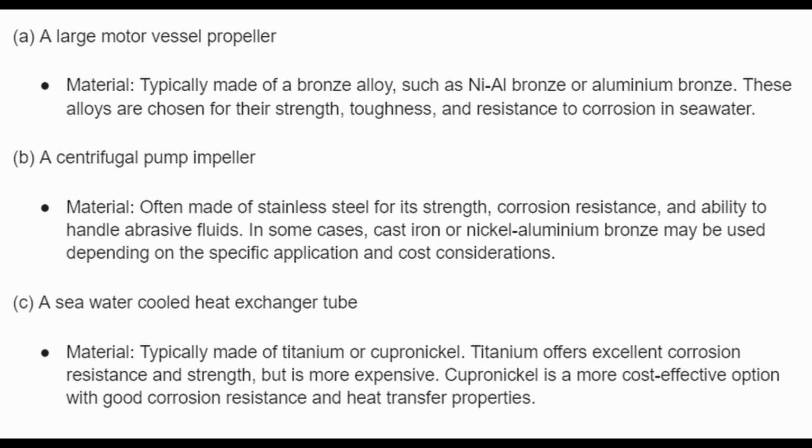B. A centrifugal pump impeller. Material: often made of stainless steel for its strength, corrosion resistance, and ability to handle abrasive fluids. In some cases, cast iron or nickel aluminium bronze may be used depending on the specific application and cost considerations.